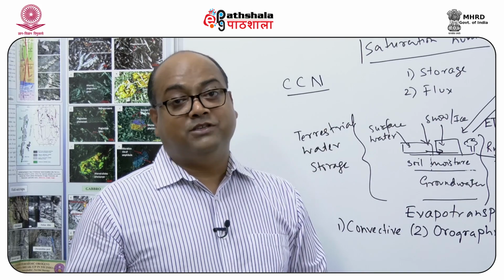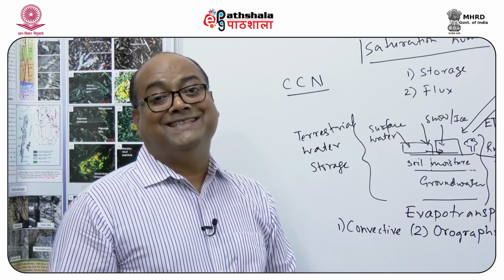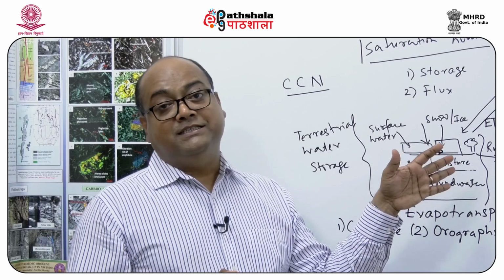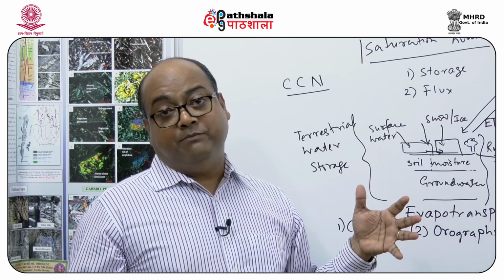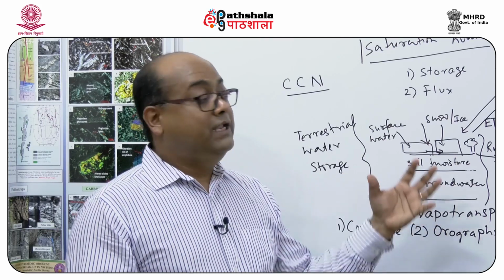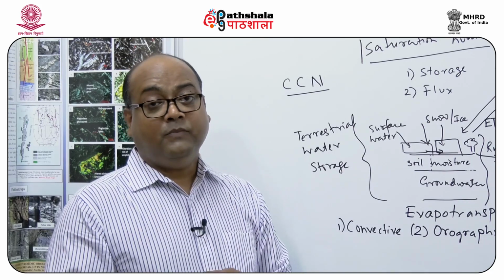There are different types of velocity meters or flow meters, and also we measure by the stage or the height of the river channel. The height of the river channel is used in something called a stage discharge relationship, by which the height of the river is converted into a volume, so we know the amount of water that is moving towards the ocean.